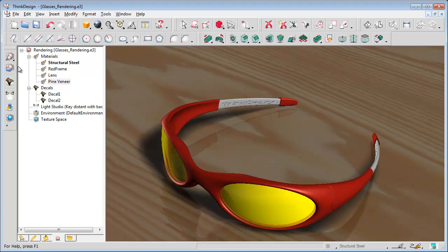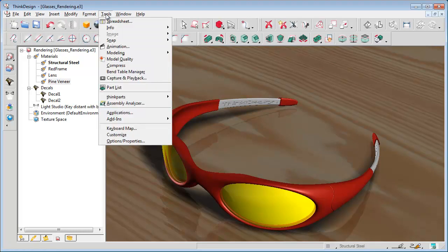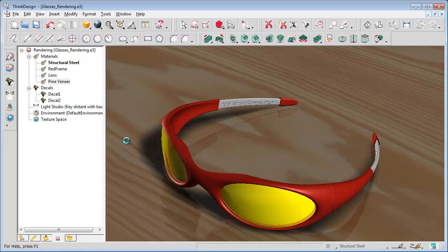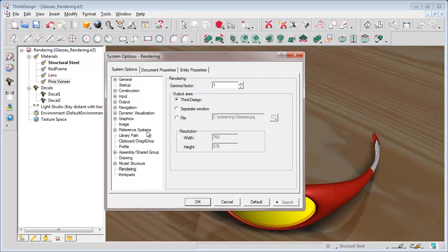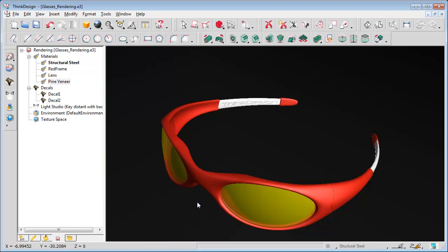When we get a satisfying image of the object, we are ready to take the final photograph. So, from the rendering options, we select again the output on the file that we had already defined. Now we can use a better quality but slower rendering, ray tracing, or the final gathering.